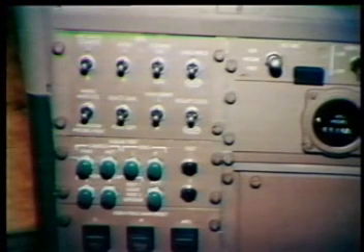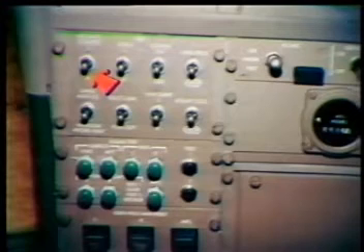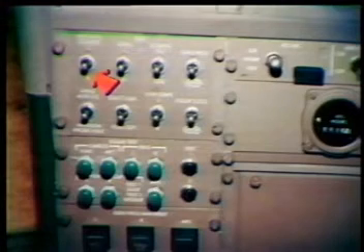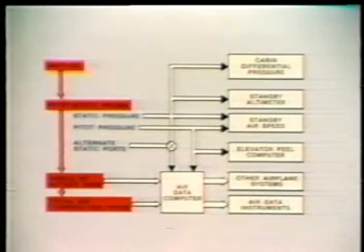On the P61 accessory panel is a switch to test the air data computers. By placing this switch right or left, the appropriate computer will send a standard test signal to its respective air data instruments. The anti-ice circuits are the remaining electrical portion of the air data system.